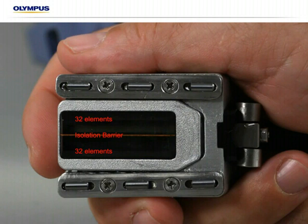Everything I've shown up to this point has been 1D linear probes, where all of the phased array elements were in a single line and not isolated from each other. The dual linear is actually 2 separate rows of phased array elements. We have 32 on each side, and an isolation barrier in between so that they can't talk. One is always dedicated to sending the sound, and one is dedicated to receiving the sound. So basically it's the phased array version of the dual crystal probe.